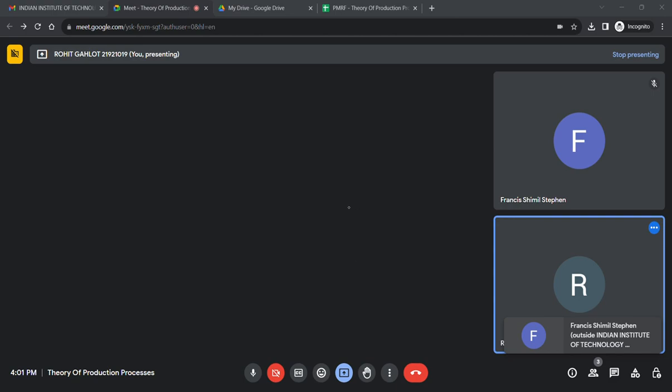but we don't want this, because if that is the case, our riser will be solidifying first, then our casting will be solidifying. This would be the reverse. If that were the case, then our answer was right. We would have said that the radius of the cylindrical riser which needs to be designed is 7 centimeter, which is right. But here our V by A of the casting is coming as 3.33, while for the riser it is coming as 2.33.